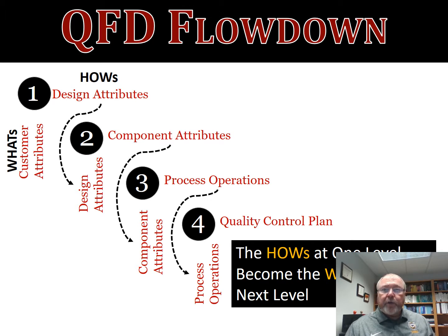When we are using QFD, it's common that we don't use a single house of quality, but that we use several subsequent houses of quality. So when we do that, it is called QFD Flowdown. That is, you flow from one QFD or one house of quality into a subsequent one, potentially into a third and/or a fourth one. So in a manufacturing setting, a tangible physical product is what you're designing and you intend to manufacture. This is what that flowdown would look like.